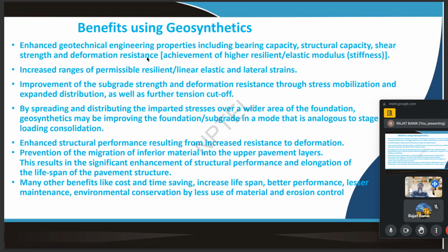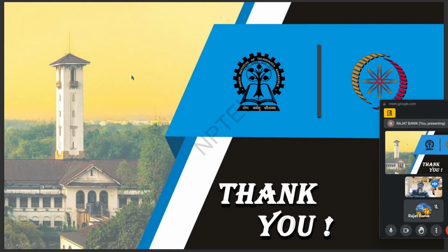So also we discussed what the different benefits are of using geosynthetic material. And we discussed that we enhance the geotechnical engineering properties, including bearing capacity, structural capacity, shear strength, and deformation resistance. And we enhance the structural performance, spreading and distribution of the stress, and improve the subgrade strength. These are the many different benefits we can get while using this geosynthetic material.